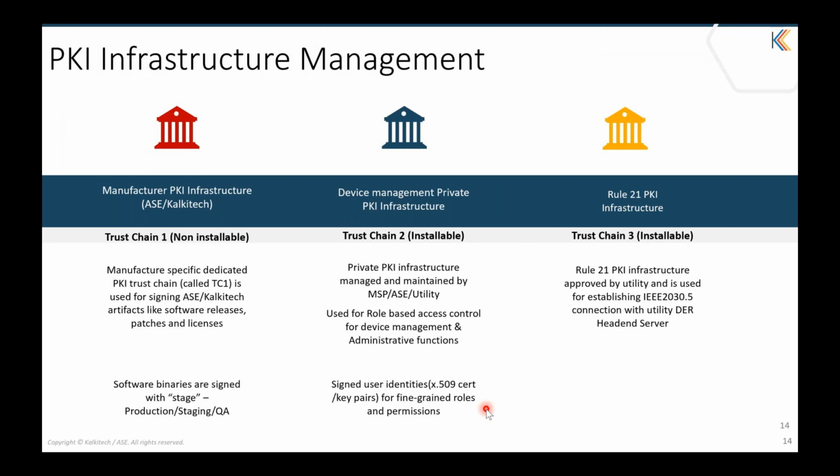There are two ways the user access check is done. It is using OCSP-based validation, or else there is one more option, as per IEC 62351-8, that is the attribute certificate based permission validation. Either of these two options can be enabled, and it helps the network admin ensure that only users who have been allotted privileged access permissions can access the device and do any operations.